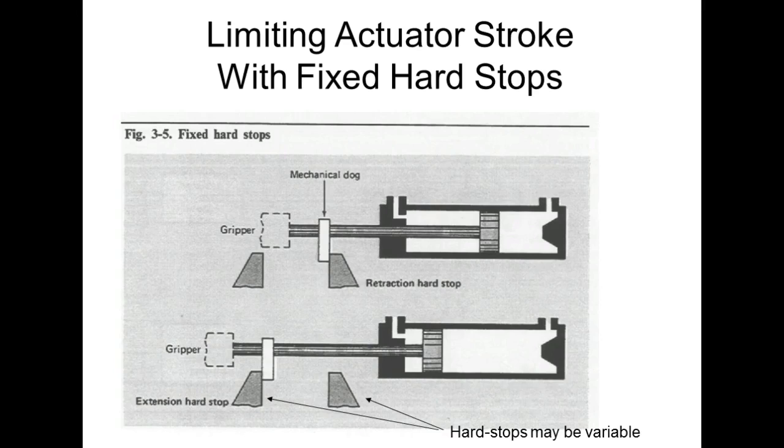Well, we could definitely do that. And if those was variable hard stops, we could reprogram them, right? Just by doing what? Just going out there and moving them. Yeah, if you're going to program these things, you're going to have variable hard stops. Your hard stops are going to have to be within the stroke of the actuator itself.